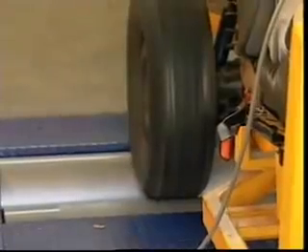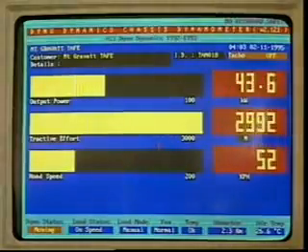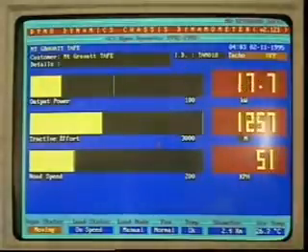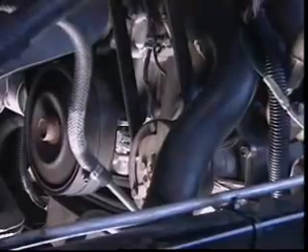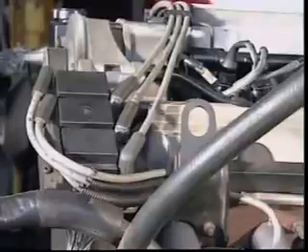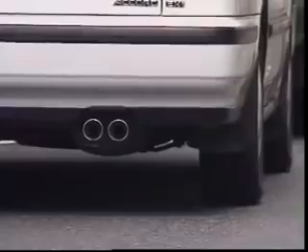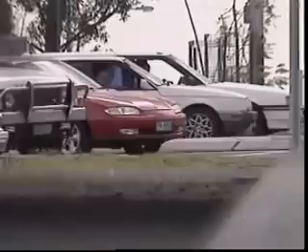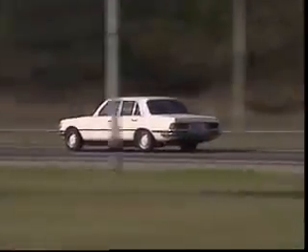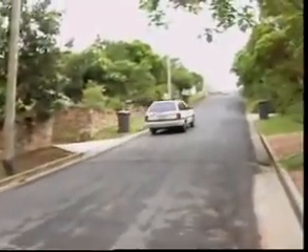Settings are made for various operating conditions according to fuel consumption, engine torque, exhaust emissions, knocking tendency, and drivability. That means, for example, that starting ability can be improved by making timing during cranking depend on cranking speed. Timing at low idle speeds can be set for low emissions, smoothness, and fuel economy. For part load operation, the emphasis is on economy and drivability. At full load, it is set for maximum torque without detonation.